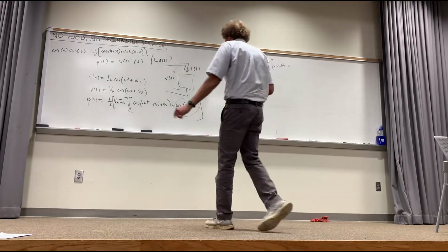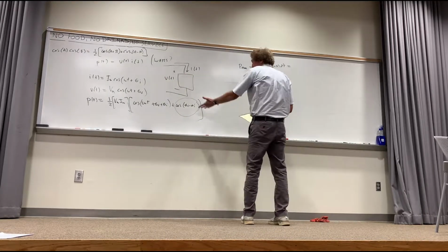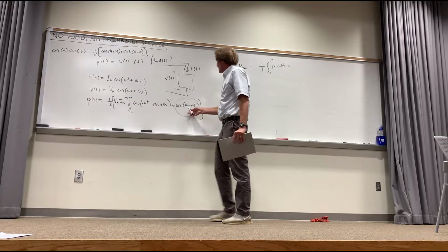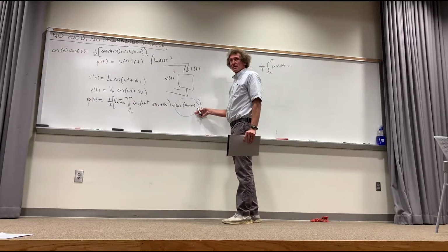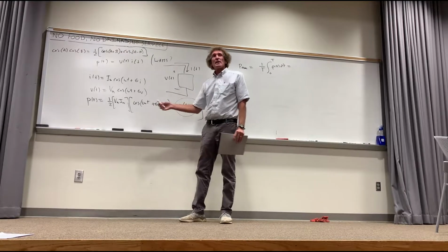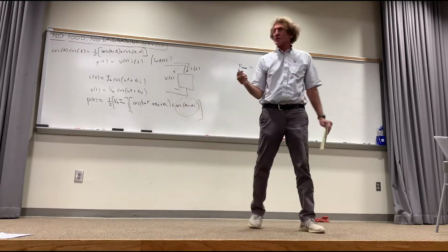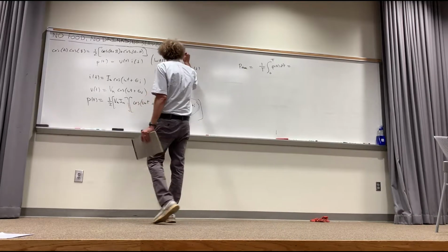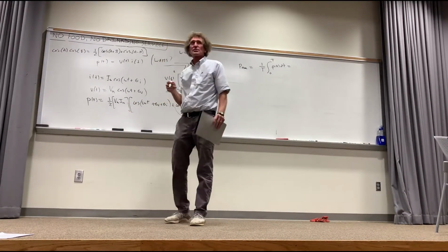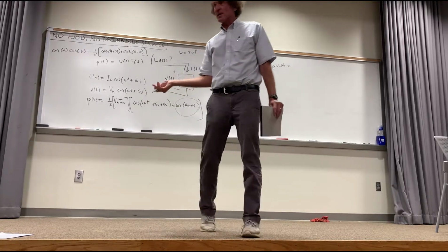If you have a given load, that will always be the same. Since it is a constant, when we take the average of that, it's just going to come out to its own value. So it will be just 1/2 Vm Im times. Remember this from last class. Now, this is variable. Omega is the radian frequency. And in case you don't know, omega is equal to 2 pi times f, where f would be in hertz or cycles per second. Are you with me?